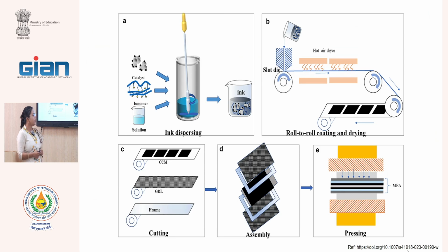So in order to recover that, what we generally do is use a hot press. We create a lot of hydraulic pressure and raise the temperature a little, so that the contact between these layers is very good, with minimal or no gap at all between the layers.